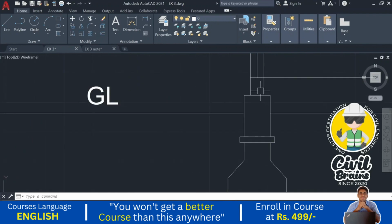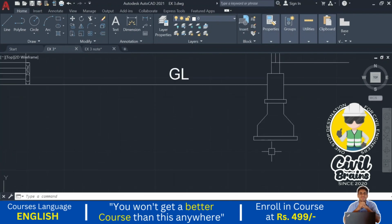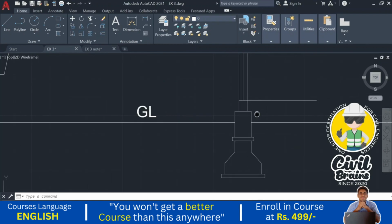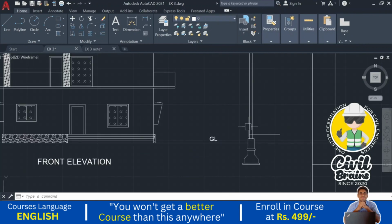Okay, so then above the masonry structure we have provided the plinth beam, and above the plinth beam there is a wall. So don't get confused here. This is the PCC and this is the PCC. This is also the excavated trench level, and this is also the ground level, 1.5 meter depth. Okay, so we have done this one. Above that we have provided the plinth beam, and above the plinth beam we have provided the wall.